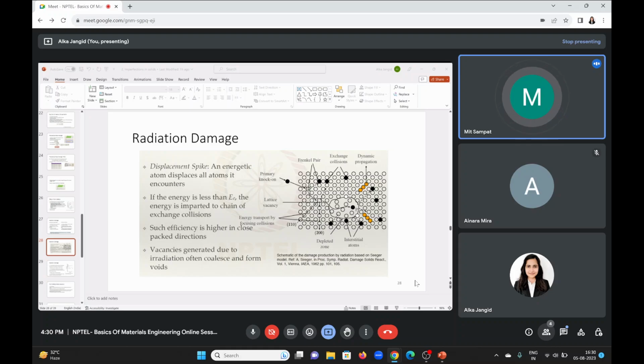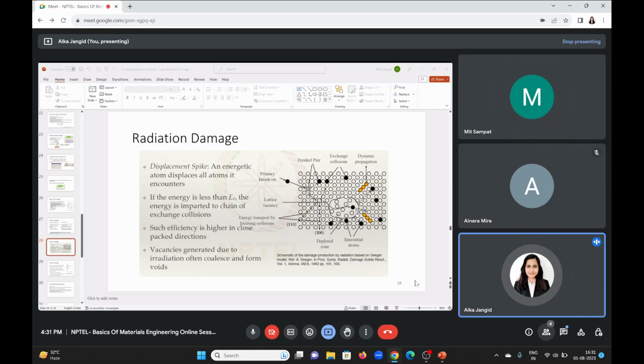So in conclusion, we have to design according to different direction forces, right? For a monocrystal material, in the final application, according to how stress is applied to your component, you have to set your strength. Your strength should be higher than whatever stress is applied.